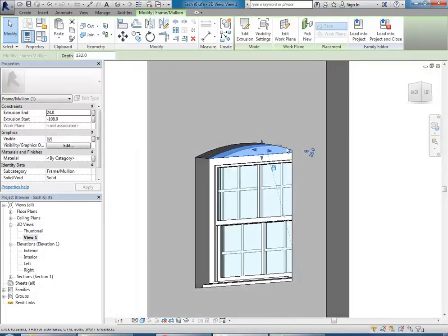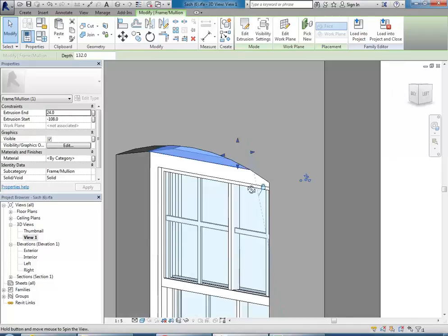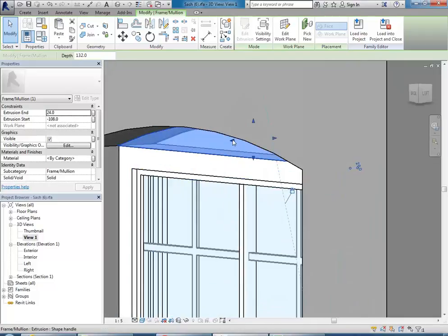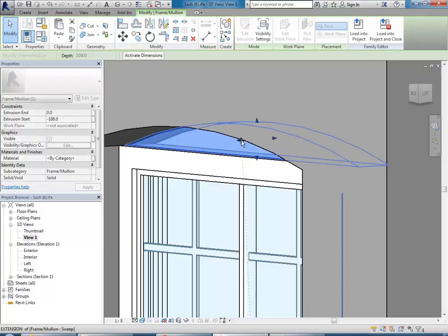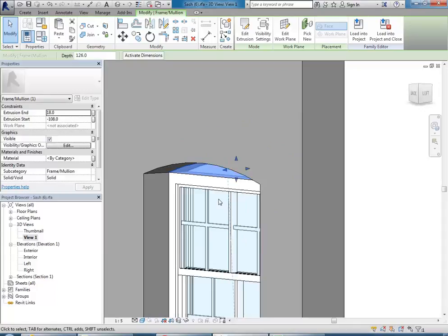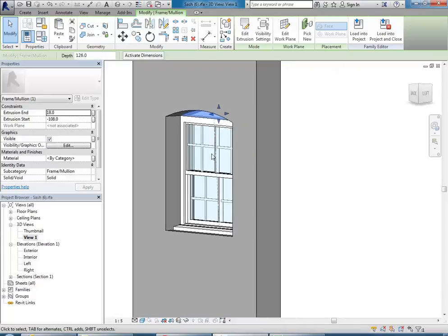and do the same on the other side. Even though it is lined up at the moment, remember that can move, so I'm going to stretch it away and then stretch it back until it lines up. Now a good trick there is to just get it right out of the way and then bring it back, so you can see when it's lined up. There it is, and that'll give the lock symbol now if I have a look for it.